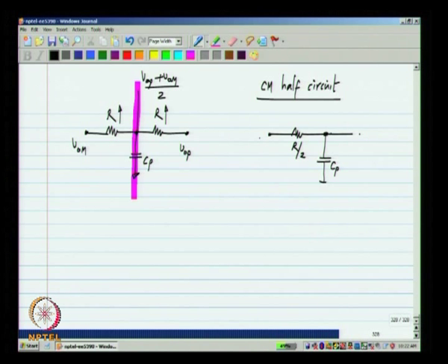Here I have the common mode output and here I have the detected common mode, and it is clear that for higher frequencies the detected common mode is not the same as this, because this is a low pass filter. Now, this can also be a problem.